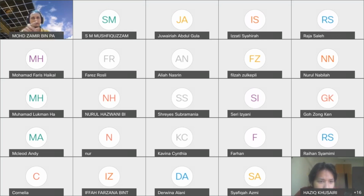So if your n is 10 to the 16 and ni squared is 10 to the 20, to find p, your p will be 10 to the 20 divided by 10 to the 16, so p will be 10 to the 4. If your majority is 10 to the 16, your minority will be 10 to the 4. If majority is 10 to the 13, your minority will be 10 to the 7, because np is equal to ni squared all the time. So we'll come to that later on.